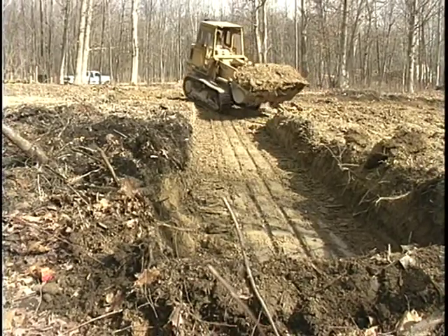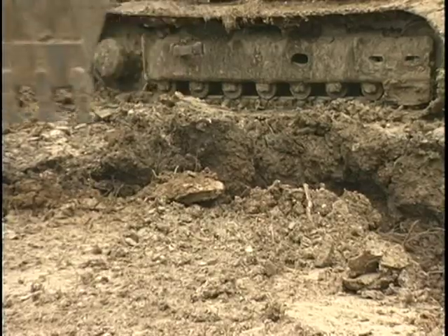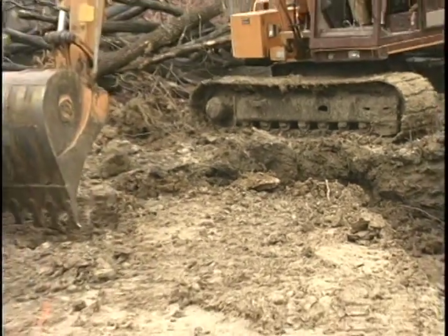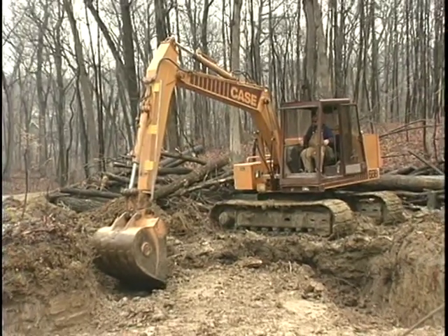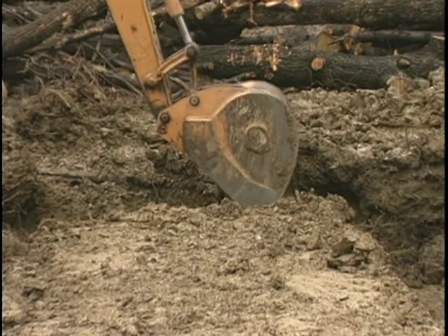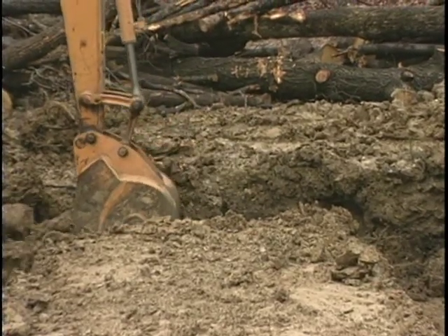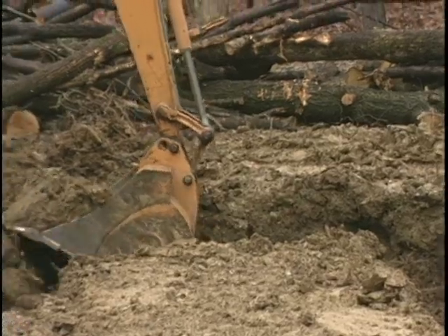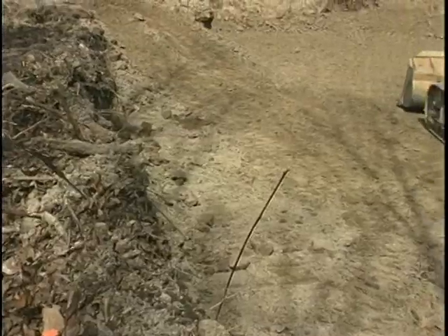During excavation, great care must be taken not to disturb virgin earth below the foundation. The heavy equipment is used to carefully scrape off soil as needed without disturbing the soil below the bottom of the footer or basement. Refilling of low spots in the excavation must be avoided because it will be difficult to recompact the fill properly. Foundation settling and cracking could result.